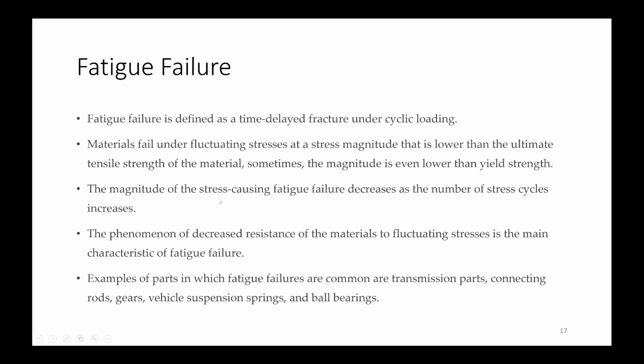The magnitude of the stress causing fatigue failure decreases as the number of stress cycles increases, and this decreased resistance of the material to fluctuating stresses is the main characteristic of fatigue failures. Examples of parts in which fatigue failures are common are transmission parts, connecting rods, gears, ball bearings, vehicle suspension springs, etc.